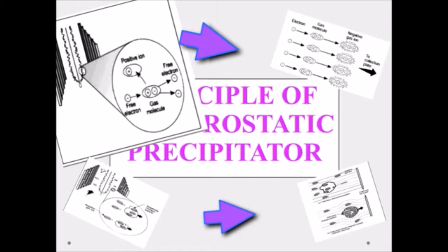Due to the formation of corona discharge, free electrons are emitted with high velocity from the discharge electrode. These fast-moving free electrons strike the gas molecules, thus emission of free electrons from gas molecules takes place. The positive ion molecules move towards the discharge electrode by electrostatic attraction. As a result, using gas molecules, more free electrons are emitted near the discharge electrode.